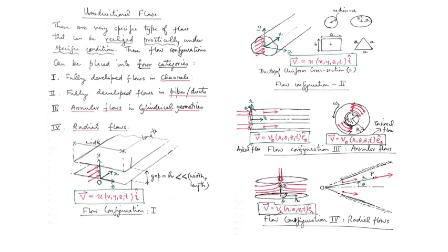So now you can see that in the annular region there are two red arrows shown. The gap between the outer wall of the inner shaft or cylinder and the inner wall of the bigger or outer pipe or cylinder is known as the annular region, and in that annular region the fluid is shown with a unidirectional motion. It is directed along the z direction. So the velocity vector is written as Vz, having only a Vz component.